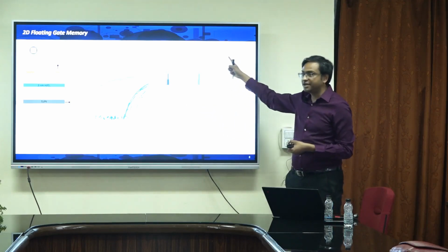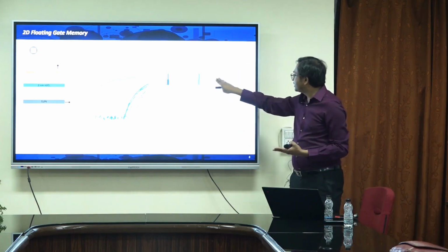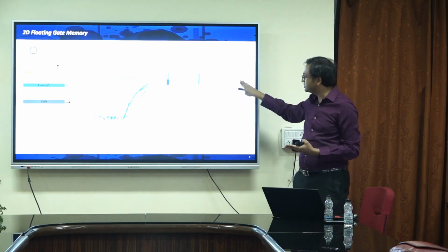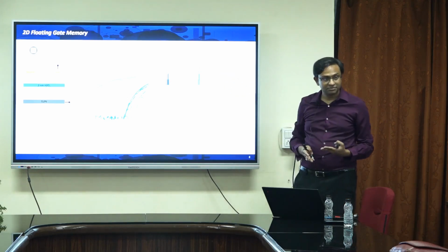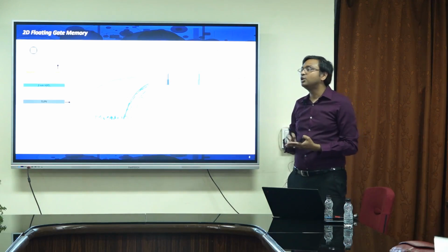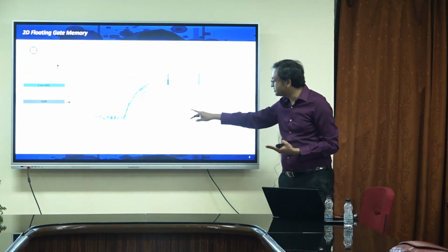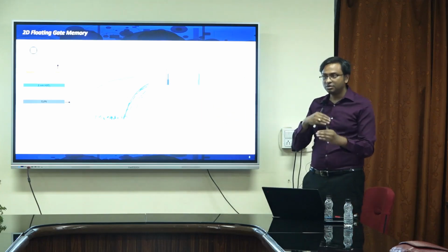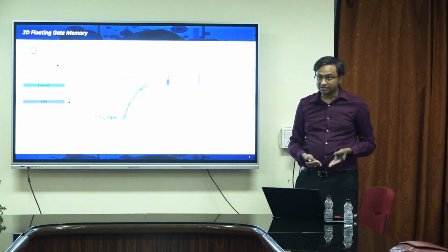Then I spoke about the memory retention. How long can you retain it? You can see that they are kind of flat. Once I put them in a particular state, they stay there for a long time. So it becomes a non-volatile or long-term memory. And I could switch between the two states multiple times: writing, erase, writing, erase, writing, erase, which is your endurance.